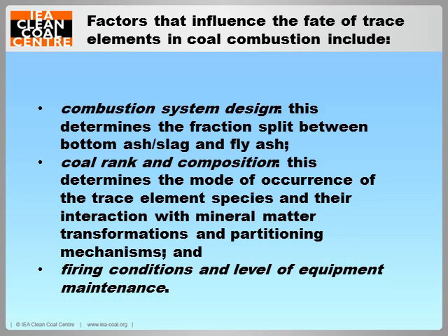Factors that influence the fate of trace elements in coal combustion include combustion system design. This determines the fraction split between bottom ash and fly ash. Coal rank and composition determine the mode of occurrence of the trace element species and their interaction with mineral matter transformations and partitioning mechanisms, and firing conditions and the level of equipment maintenance.